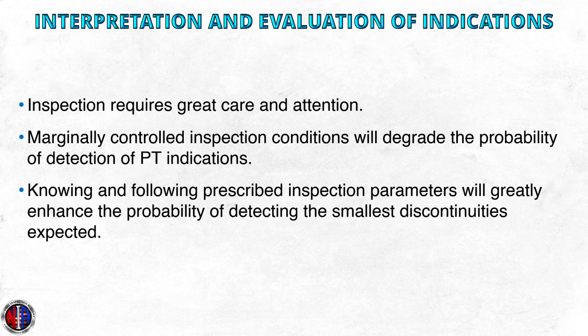Interpretation and evaluation of indications. Inspection requires great care and attention. Marginally controlled inspection conditions will degrade the probability of detection of liquid penetrant indications. Knowing and following prescribed inspection parameters will greatly enhance the probability of detecting the smallest discontinuities expected.